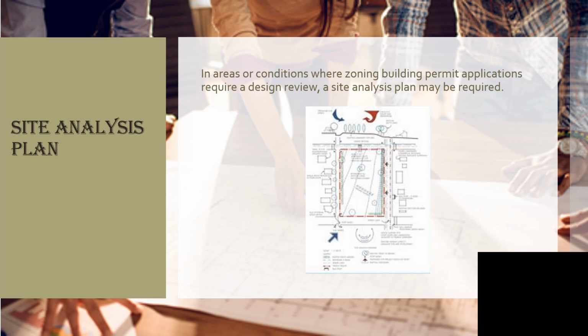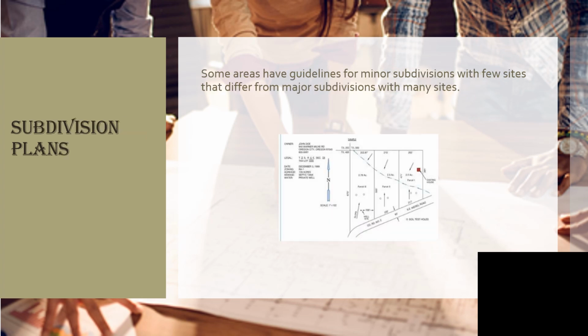Site features such as existing structures and plants on the property and adjacent property. Scale. North arrow, property boundaries, slope shown by contour lines or cross-section or both, land legend, traffic patterns, solar site information if solar application is intended, pedestrian patterns. This is a typical subdivision of land with three proposed parcels.